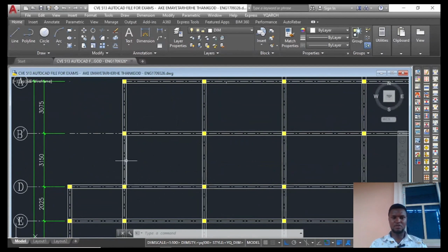Now let's go for this other one here, the other short side. On this side, to your right, there's a beam. I mean, to the right is continuous. But to your left, there's nothing there. You understand? Because of that, this panel becomes one short edge discontinuous. That means it does not have continuation. This is the last beam here. It's the short side that is discontinuous. I hope you're fine with this.